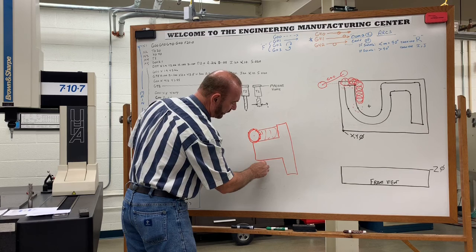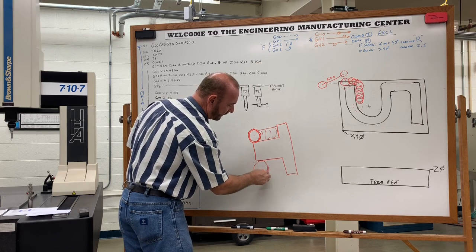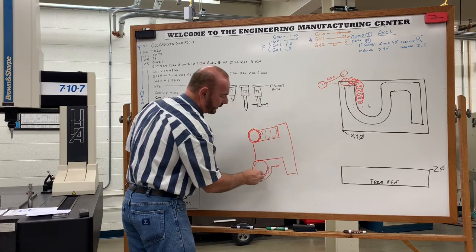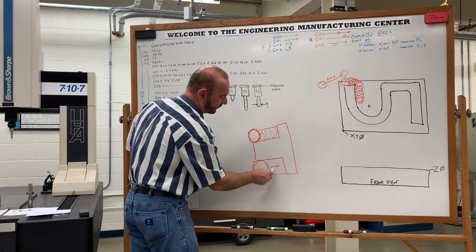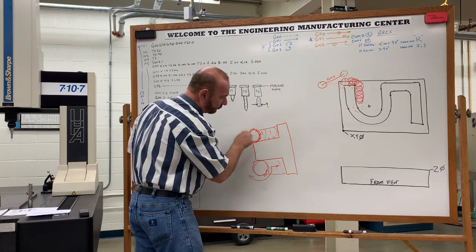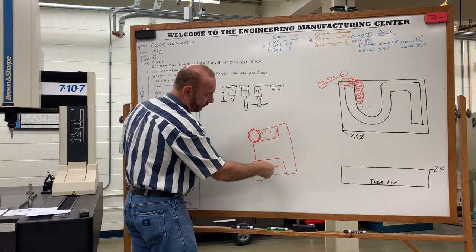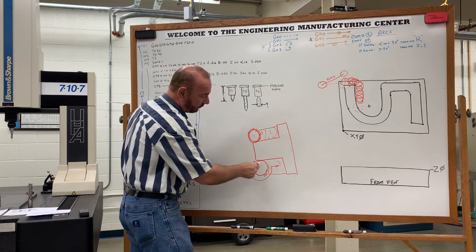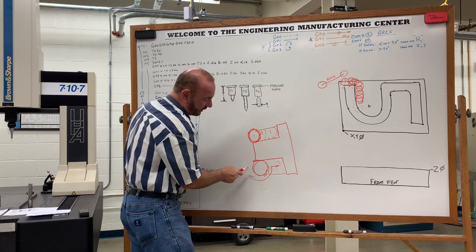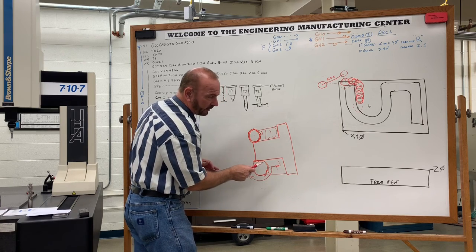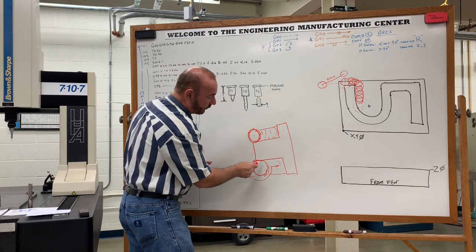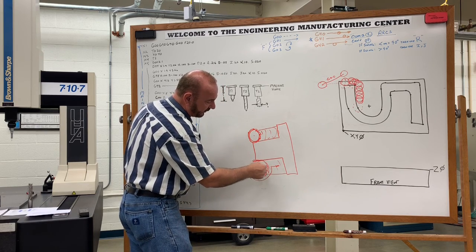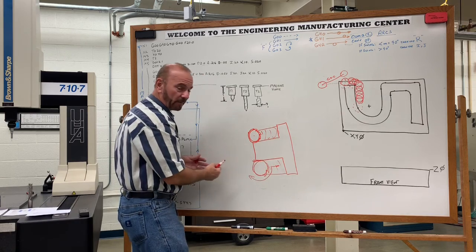So let's take the same cutter, same size diameter, same teeth, same rotation, and same direction of travel. But in this case now, when it's trying to cut all this material, instead of it wanting to roll and drive into the part, it wants to roll away from the part. So on a manual mill, you're controlling that cut, and it really has nothing to bite back into, because as you're feeding it into the material, the material is being taken away, so it has nothing to bite on to run back at you.